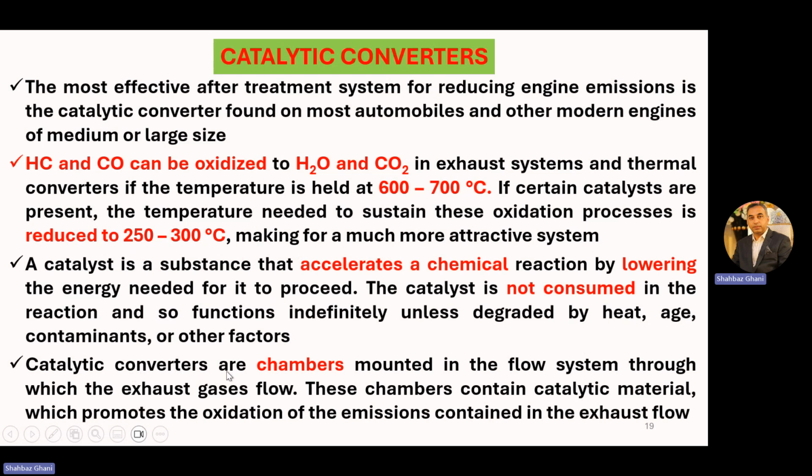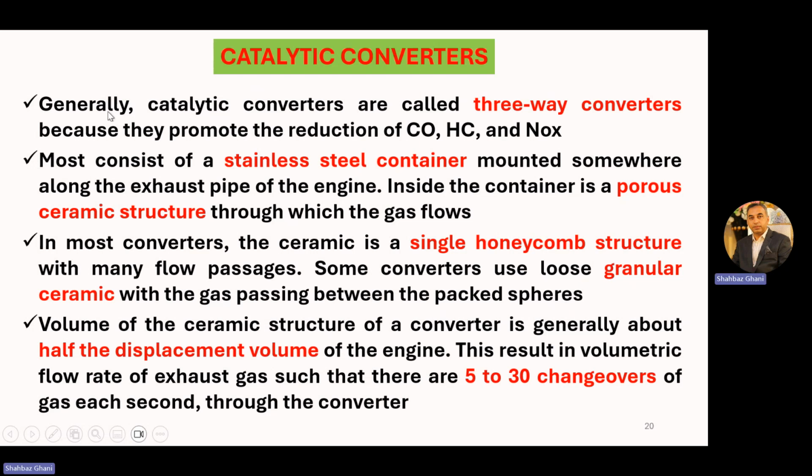So the catalytic converters are basically like thermal converters. They are chambers mounted in this system. These chambers contain catalytic materials which promote the oxidation of the emissions contained in the exhaust flow. Generally, catalytic converters are called three-way converters because they promote the reduction of carbon monoxide, hydrocarbons, and NOx.